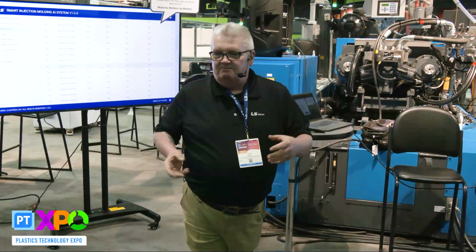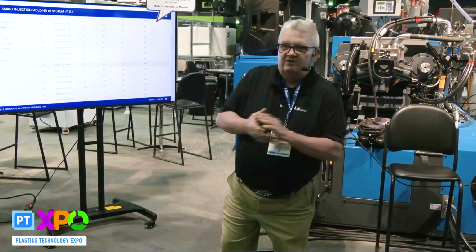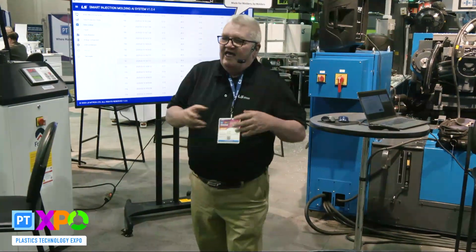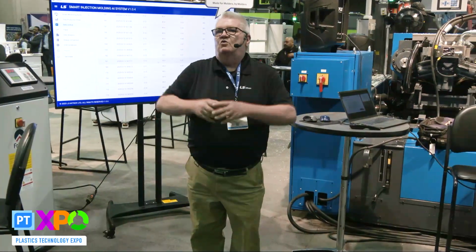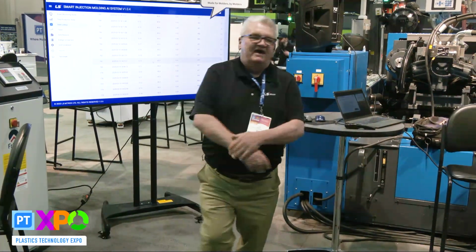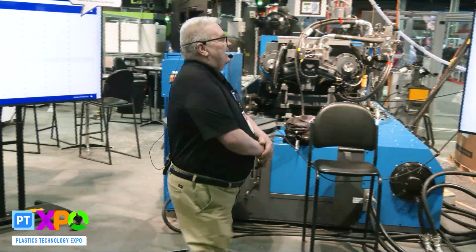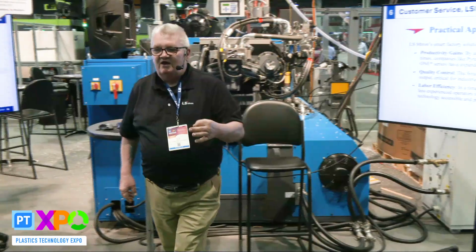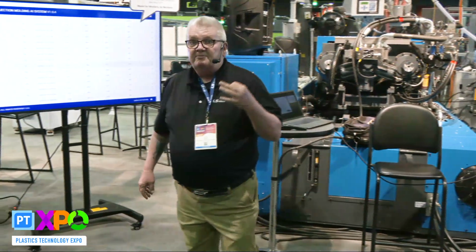Now there are safeguards in place that we tie into the molding machine, all the peripheral equipment, hot runners, thermalators, dryers, so that once we see a deviation in that, of course, it would alarm out and identify that we have a potential problem. That will make our shot repeatability there. It will bring a quality part in.